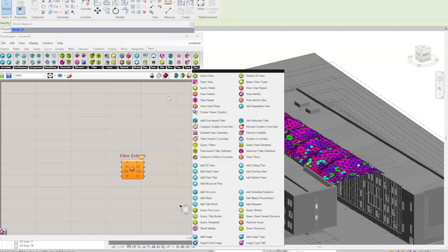That's all we can do. The same thing goes for a scope box. There isn't an API for creating a new scope box. You can copy other scope boxes, and you can set the scope box parameter that controls those grids and levels. But we're always going to be limited by what Revit allows us to do.